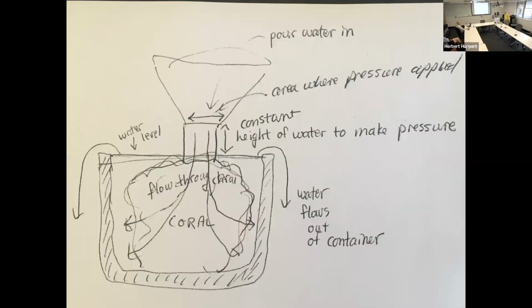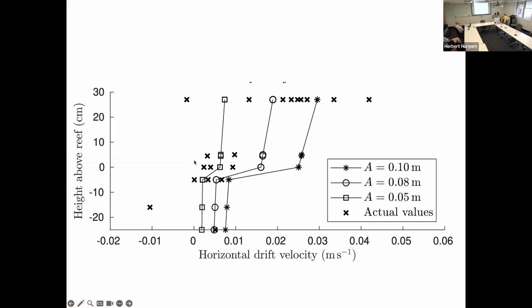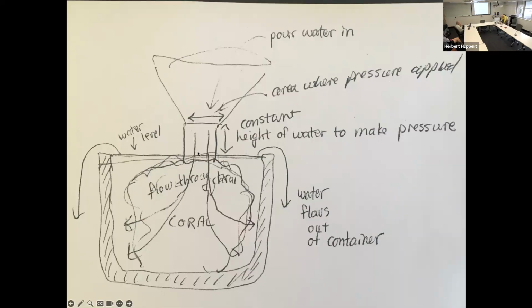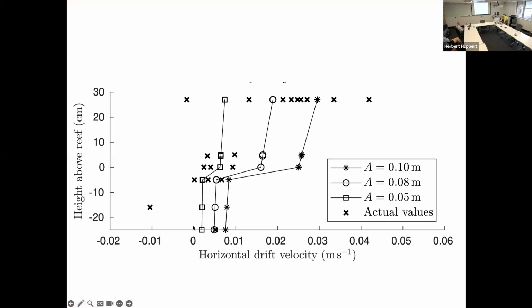And the permeability we measured by putting it into a big flask and then putting a funnel on top here. We could keep this funnel at a constant level of water that would flow through, and so we know what the pressure is that's driving the flow. We know the rate at which it's flowing, and so from that we can determine the permeability of this.